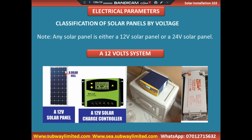If you count these cells here, you will notice that there are 36 in number, and each of the solar cell here is 0.5 volts or 0.45 volts. And if you connect this in series, you will certainly have a voltage of between 15, 17, or 21 volt, depending on the intensity of the sun.